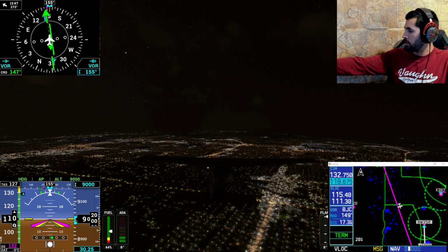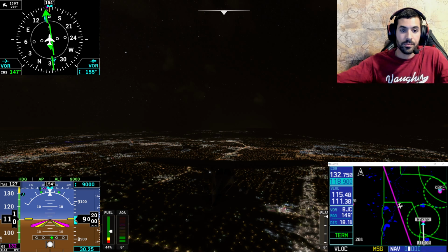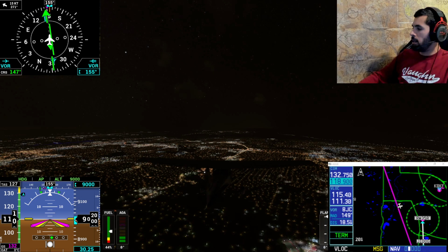The next one is instruments in our wire checklist. Instruments is just making sure that you have your VOR or ILS, whatever you're using, set up. We're going to be doing an ILS approach, so we do need a VOR receiver with glide slope capabilities. So with that, we can basically follow down on a specific glide slope all the way down to the runway without having to worry about hitting obstacles, getting too low, especially if we can't see anything.